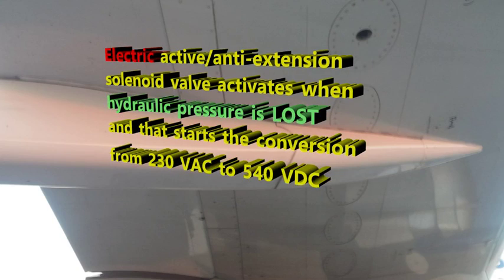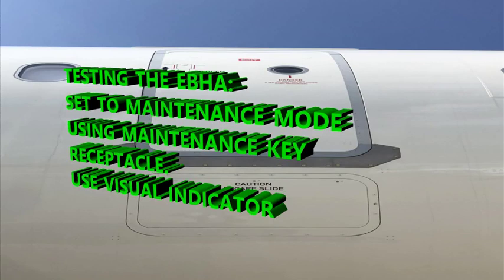And here it's doing the same thing with changing alternating current to direct current, only our direct current is not 28 VDC. We're jumping to 540 to supply power for different areas, different components. Okay. All right. So just so you know, that's what is involved with the electrical backup hydraulic actuator and the maintenance on it. It can be set to a maintenance mode. There is a key receptacle, and that's used for selecting the maintenance mode, so that you're aware of that.